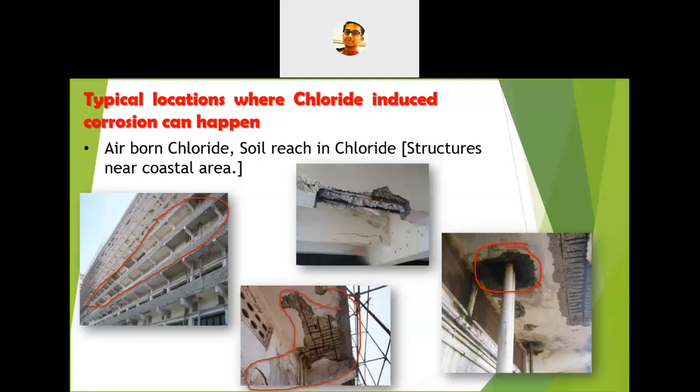So suppose the sewer pipes and all are going through; you can refer to the rightmost picture at the bottom. You can see that in most buildings they provide some gap in between the pipelines. But if you don't provide gaps, especially if the pipes are made of plastic or PVC, then when the water flows through the pipes, they suffer from some vibration force, or there may be some movement in the pipes.